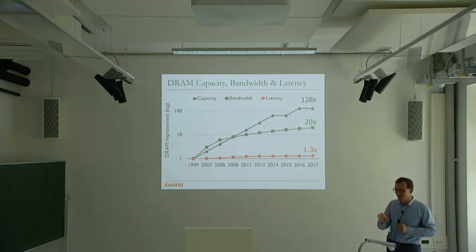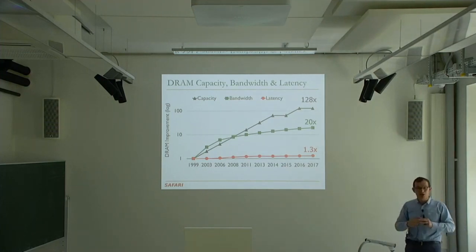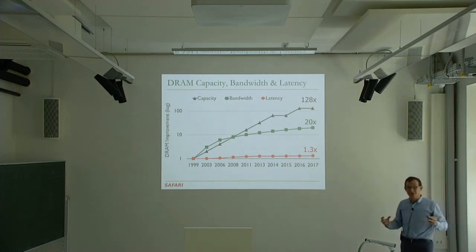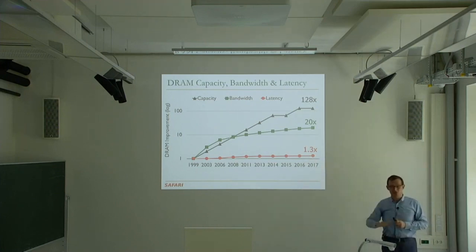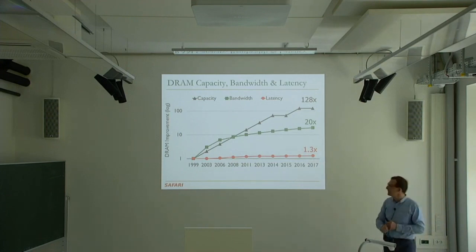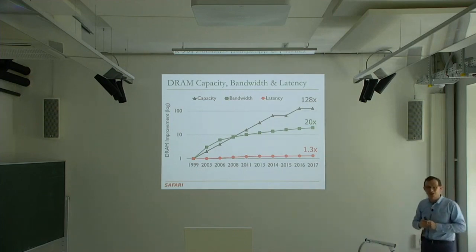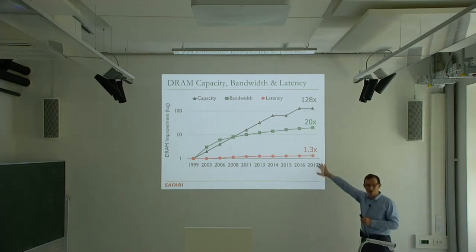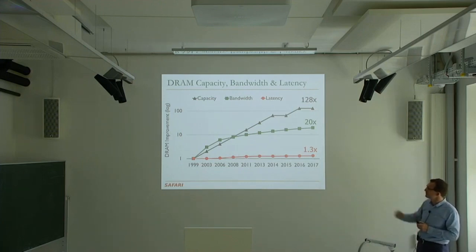I designed a mechanism that's energy efficient, that can tolerate the latencies without increasing the complexity of the processor a lot. And I like that idea, but I think we still need to do something more fundamental. As opposed to tolerating latencies with caches, prefetching mechanisms, multi-threading, better out-of-order core designs, maybe we should just reduce the latency in the memory so that we don't need to design all of those complicated mechanisms, right? And if you push processing inside the memory, fundamentally, you have a bit lower latency over there. But still, you need to do more to reduce the latency of the access of the data.